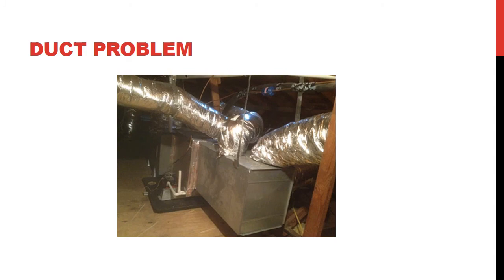Duct problems, again. Look at this duct. You can see that the duct is not really done correctly here. Part of it is closed and crushed, so that's not a really good duct system. I'm probably losing a lot of pressure in here. And you can see some parts are crushed and not open completely.